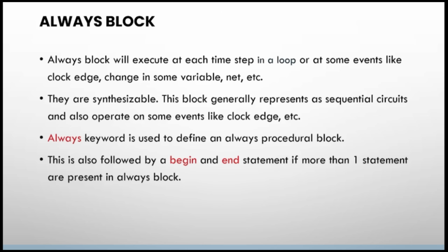Also, one more difference between initial and always block is that always is synthesizable. Which is why we mostly use always block in RTL code, and we'll use initial block in test bench writing. When you are writing a test bench code, you'll be using the initial block, and when you are writing the RTL code, you will be mostly opting for always block. But this is not a rule. Generally, when you are generating clocks, in such cases when you want to repeat the execution n number of times, you will be using this always block.